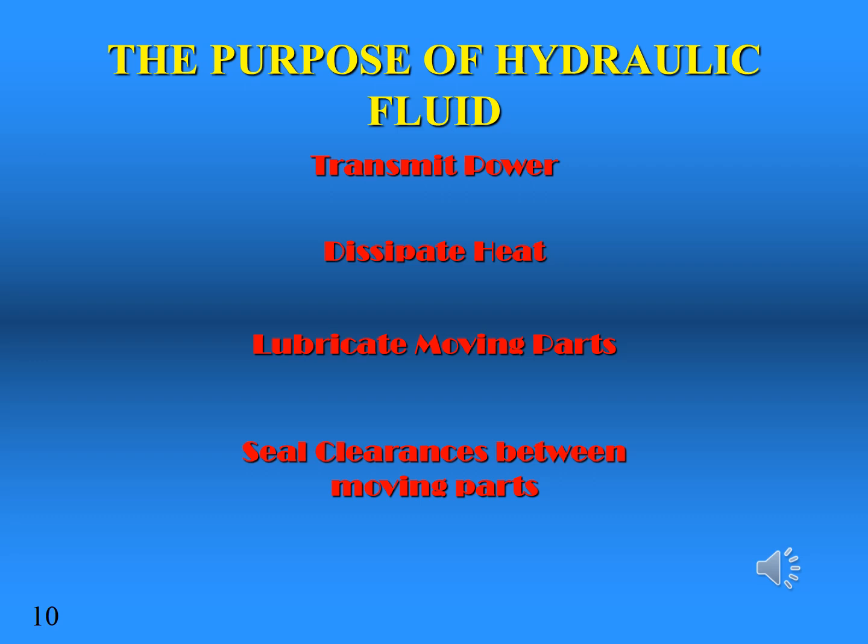To be most efficient in its role as a power transfer device, hydraulic oil needs high bulk modulus, which is high resistance to reduction in volume under pressure, and high viscosity index, which is the low rate of change in viscosity with temperature.